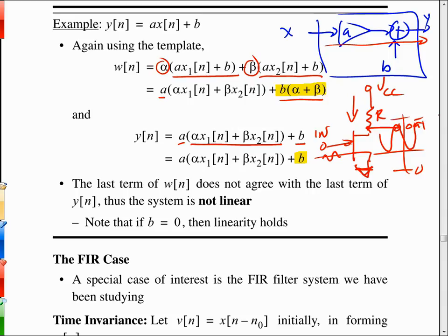But if we put a coupling capacitor in this whole setup, which is more typically what would be done, and we first learn about this in Electronics 1, call it C sub C for coupling capacitor, then you block DC, and then the waveforms are right about 0, both from the input side and the output side. So you can make it look like a linear system then.